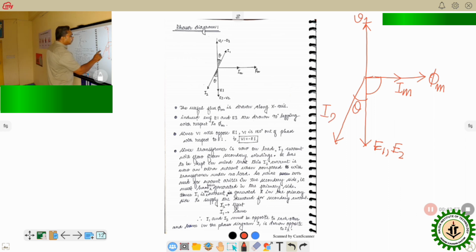Now I have to understand another thing. When we understood the operating principle of the transformer under load, the secondary flux opposed the primary flux, the flux in the core got reduced, E1 got reduced, and the induced voltage got reduced. So the opposition offered towards V1 got reduced. V1 is opposed less, so V1 can drive in one extra current.